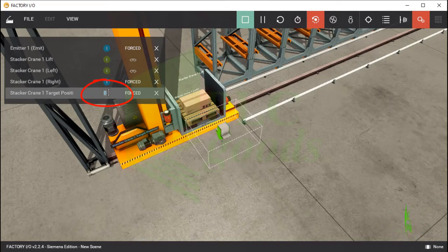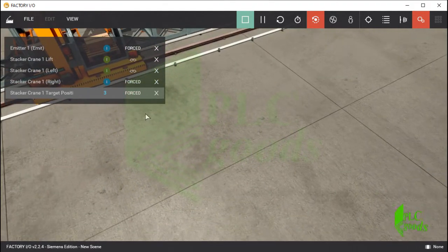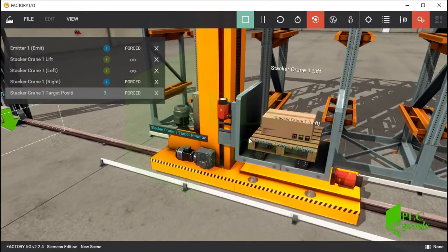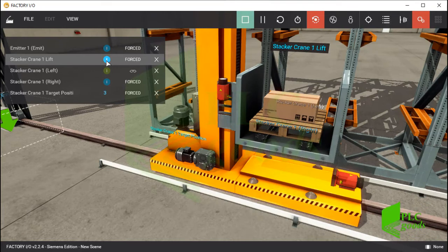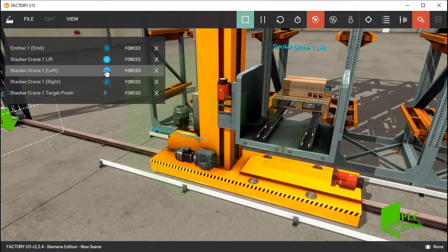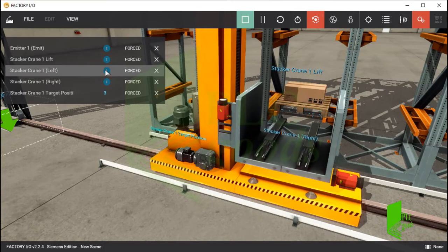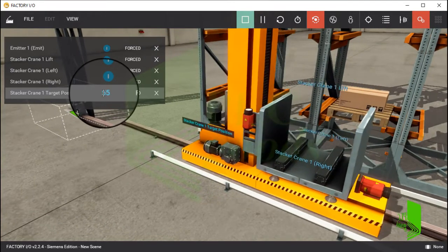It can accept an integer number from my controller. Now, let me write number 3 manually and test it. As you see, the crane is moved to position number 3. Other positions are accessible by entering a number from 1 to 54. Note that, if I enter number 0, the crane won't change its position, and I must use number 55 to go back to the default position.